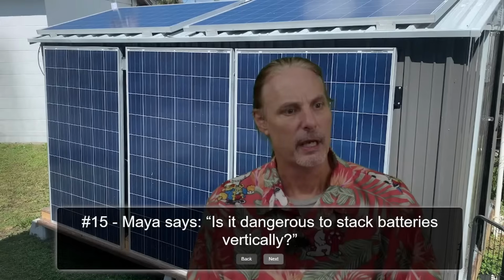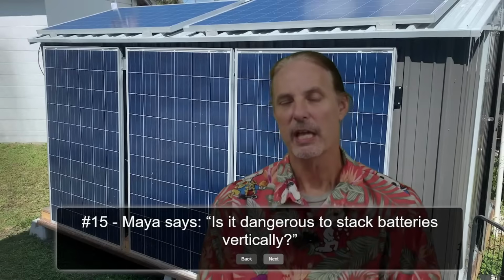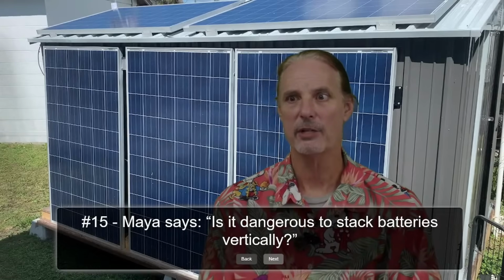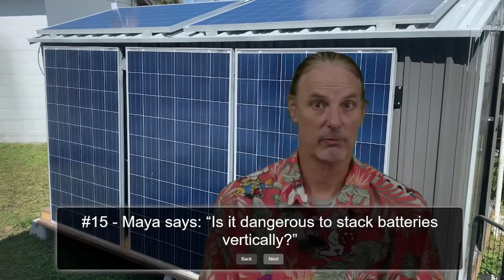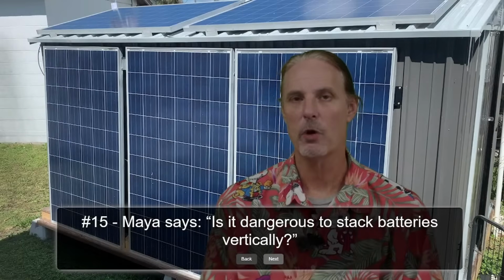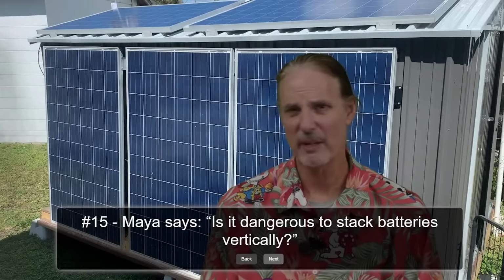Maya says it's dangerous to stack batteries vertically. I would agree, it is dangerous to stack batteries vertically, unless the specs for each battery will tell you how they can be laid. I do have batteries stacked vertically in a rack. They're made for that. Rack mount batteries are made to be stacked vertically. But if you are just stacking them one on top of each other, I would check the manufacturer specs on that. The way the cells are laid in the cases and stuff is very important.